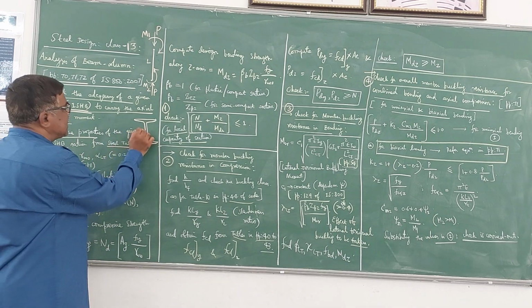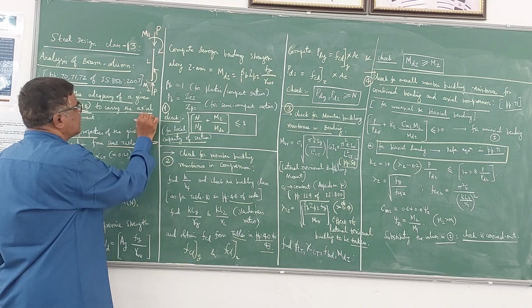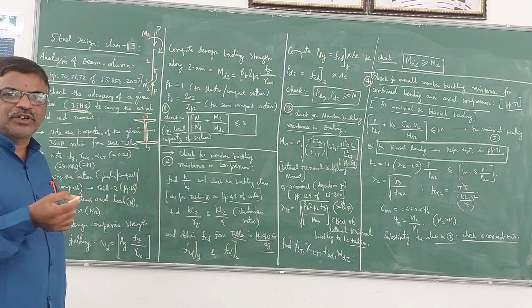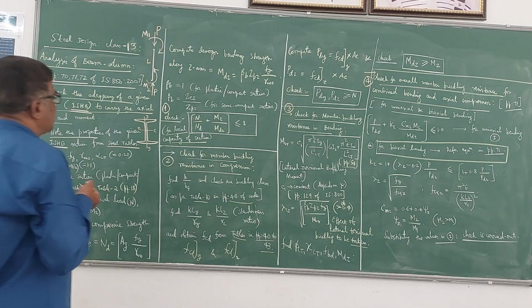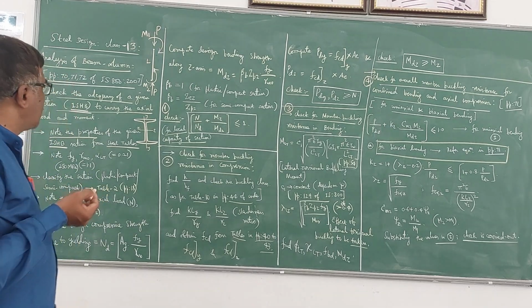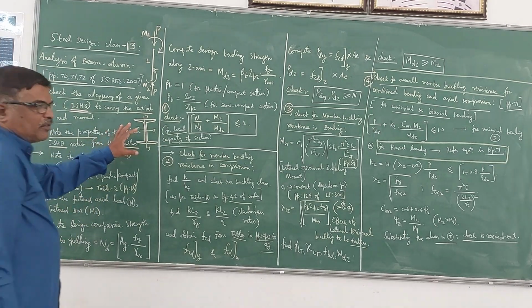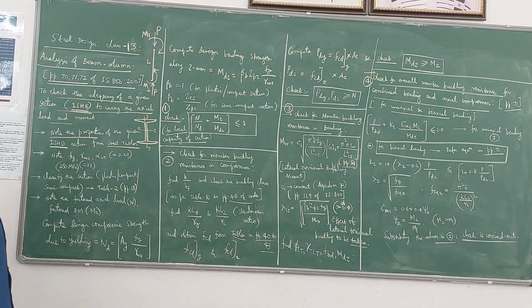Then Izz as well as Iyy. Then you may have to get the values of Zpz, the plastic section modulus about the Z axis, and the elastic section modulus about the Z axis, Zez. All of these are readily available from the steel tables, so note them down for that particular section.